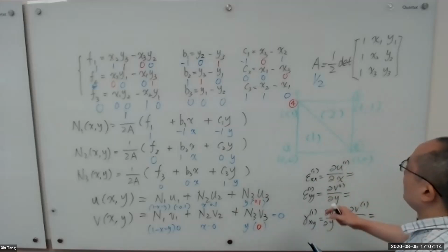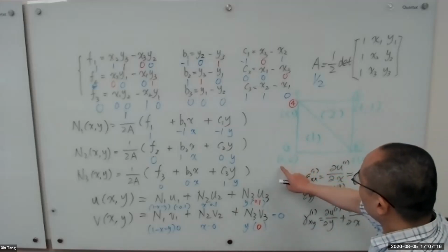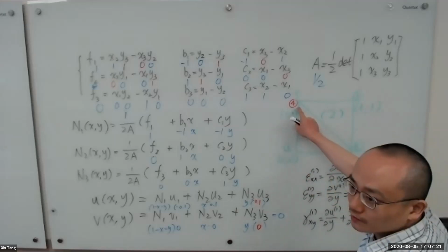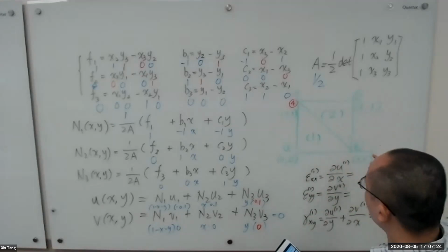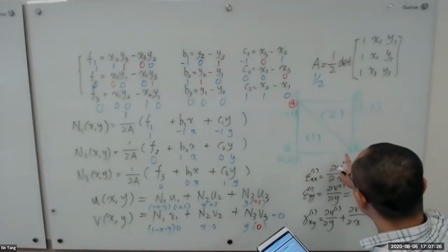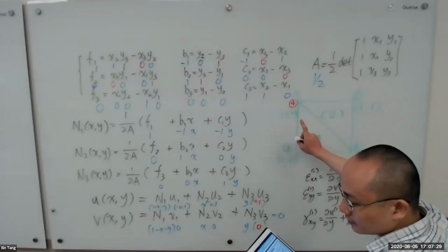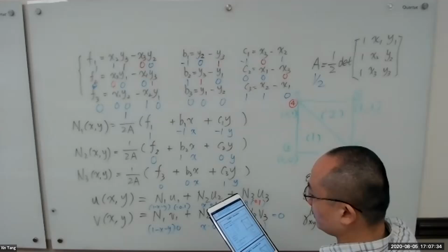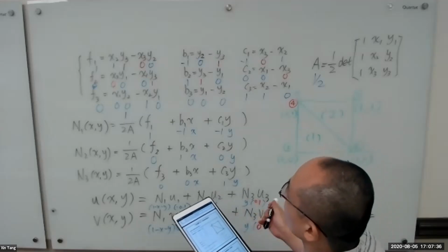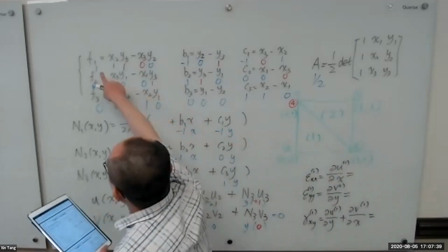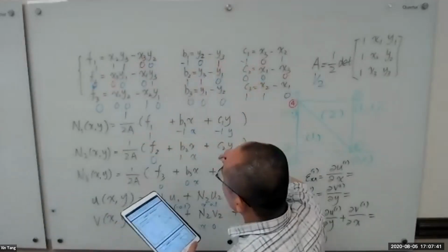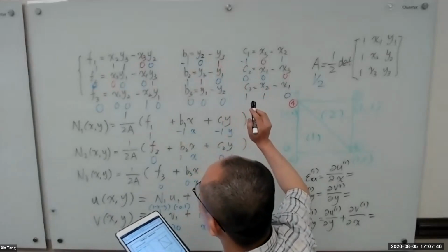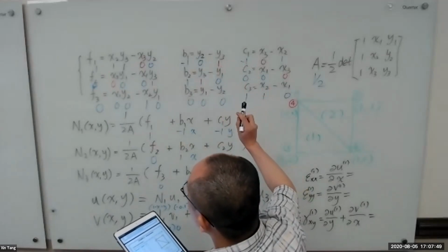Now you know the coordinates of node 1, node 2, node 4. We also know the displacements of node 1, node 2, and node 4 already, right? Now, let's firstly calculate the shape function. To calculate the shape function, we need to calculate f, b, c. The formulas I wrote in black color.